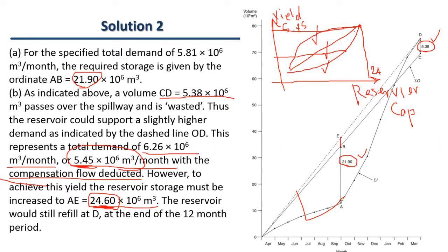This kind of curve is really important. Why? For decision makers, the reservoir capacity has a connection with the cost, and you can calculate the cost of the reservoir, and the yield is the benefit. So the benefit and cost analysis can be easily done with this curve. Decision makers, for example those planning the dam construction, could be consultants, clients, or policymakers, and see that with different yields you can benefit more people. But you might have more problems with the capacity.